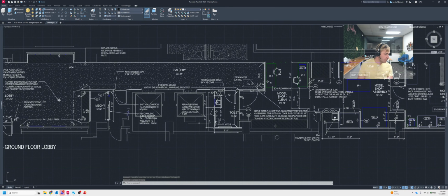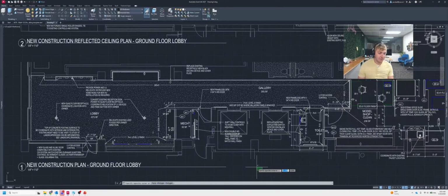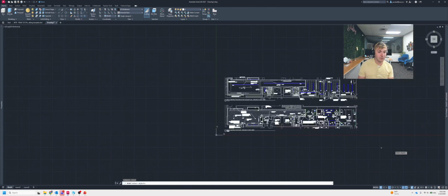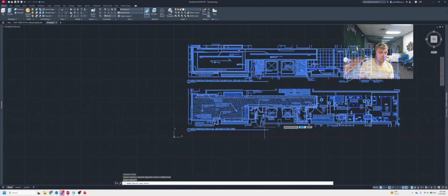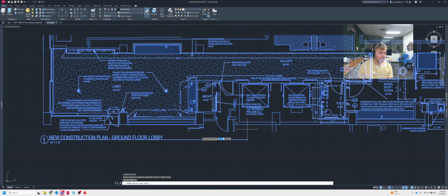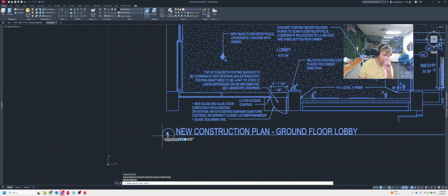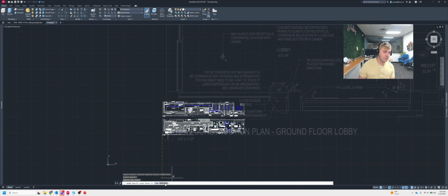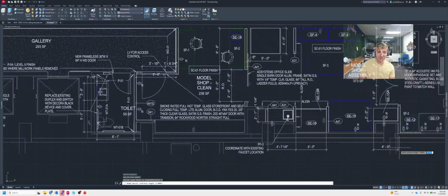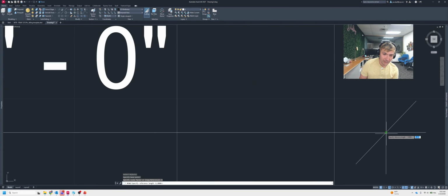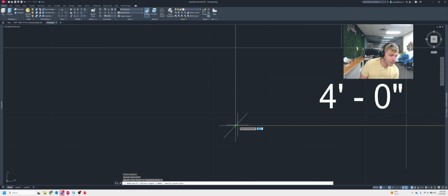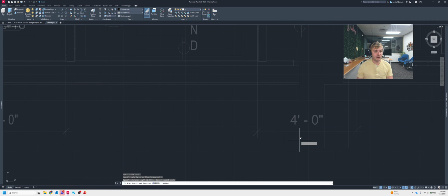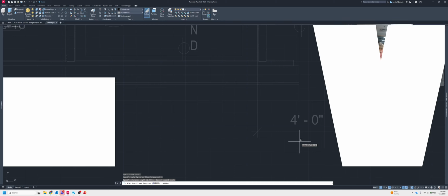All right. So before we go about deleting any dimensions, let's use the scale command. Highlight everything here, and then we are going to specify a base point, which can be anywhere. There's no rhyme or reason to that necessarily, but then you want to go down here and hit reference. Now here, when you go to reference, you're going to want to pick 2 points that are known. So there and there, I know between those 2 points is 48 inches.